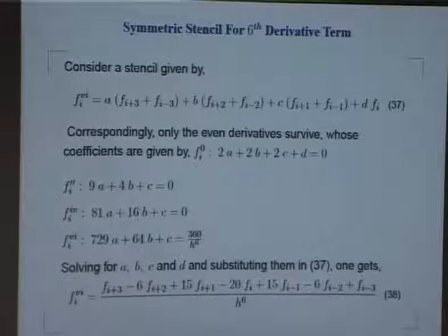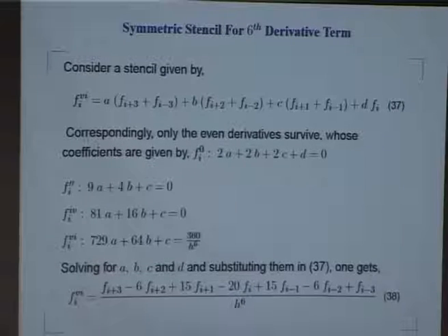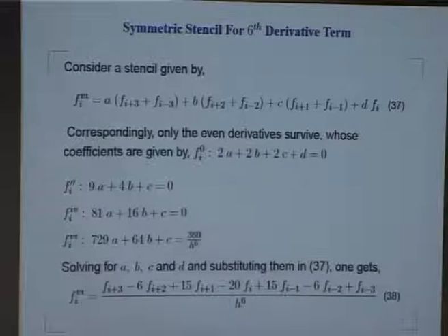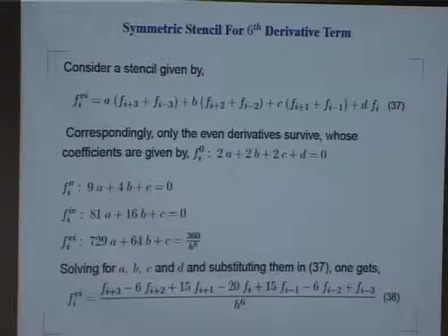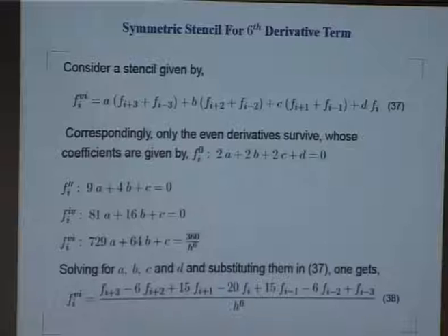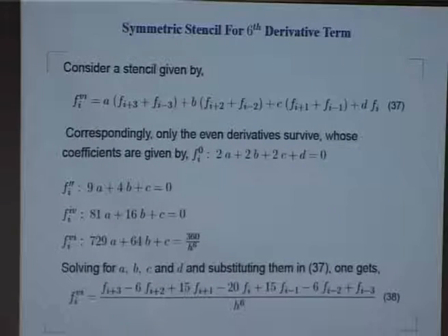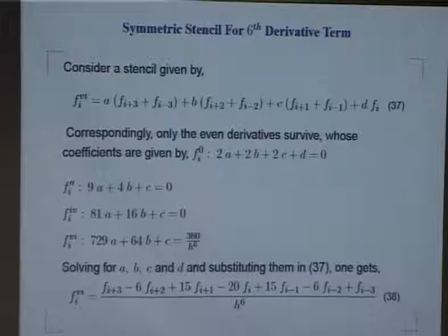And if I want to do third order upwinding, then I will do it with a CD4 or central differencing scheme of 4th order for the convection term, and I will add a 4th derivative term as a numerical dissipation. So, that is the whole idea.